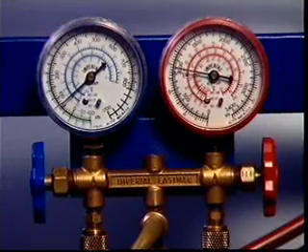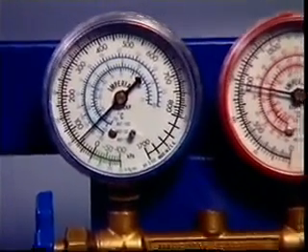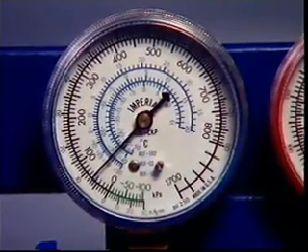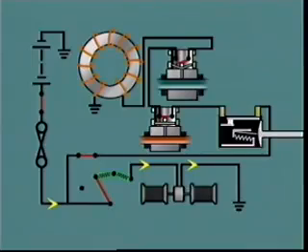Low pressures can occur in air conditioning systems when the refrigerant has escaped. With no refrigerant flowing, lubricating oil flow is also reduced, and this can damage the compressor. Low pressure causes the contacts in the low pressure switch to open and break the electrical supply to the compressor clutch and stop its operation.